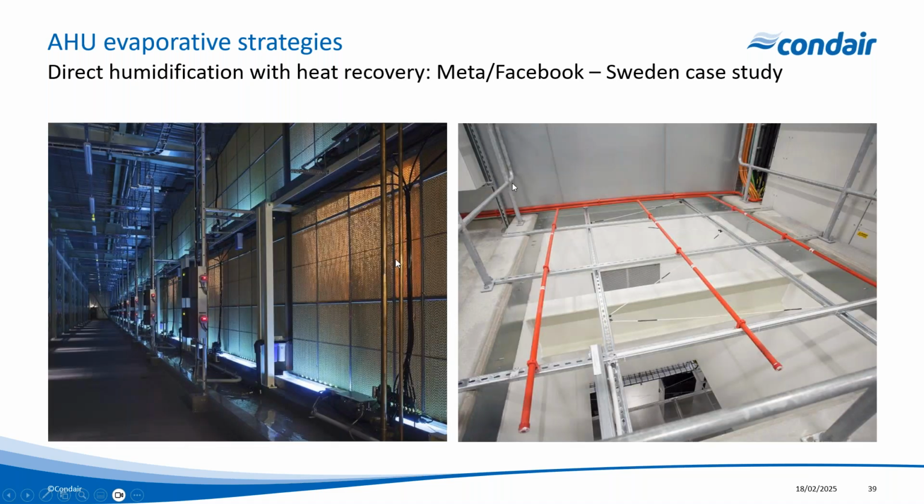So a couple more images here. The image on the left, you can see the evaporative media system. Turn the lights off here. You can see a slight glow coming from the bottom of the sumps, and that's actually the UV water sterilization system that we implemented here. We talked about hygiene for these types of systems, and UV treatment is a really common hygiene control method used in evaporative cooling systems. And then the other image here on the right just shows the air supply into the data halls.